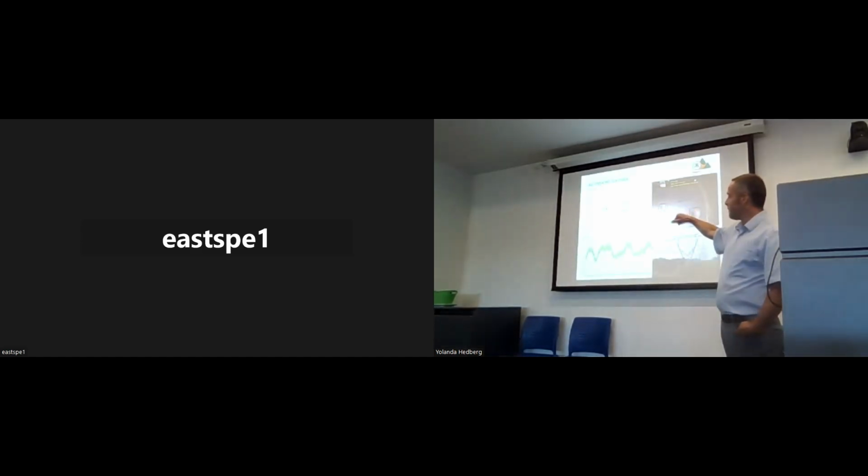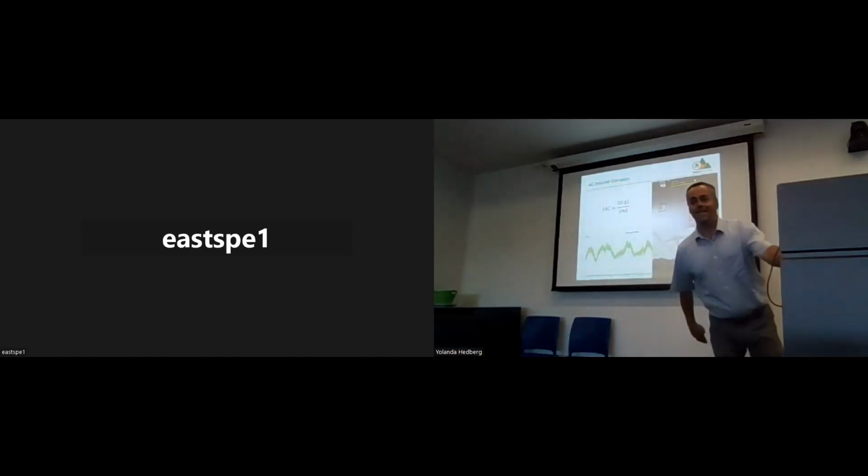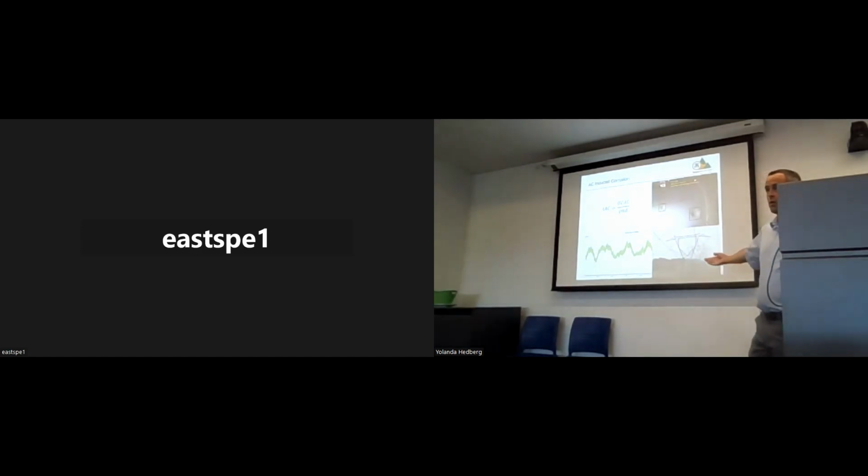In the formula, we measure the voltage, and that's right here. Power lines fluctuate, depending on how much power is on the line, what the load is. We would take the peak. Right here, we got 1.2 volts AC that is induced. This is measured. This is not theoretical.